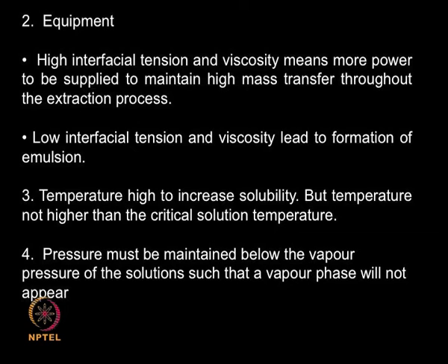Temperature, if I increase the temperature, solubility of the phases also increases, but then I do not want to increase the temperature so much that it comes closer to the critical solution temperature. Pressure, I should maintain the pressure below the vapor pressure of the solution, otherwise I do not want the solvent becoming vapor or some of the feed components becoming vapor.